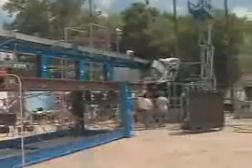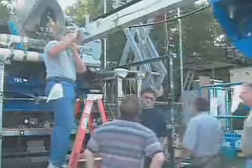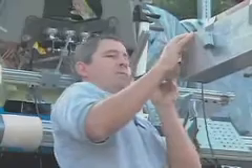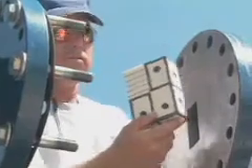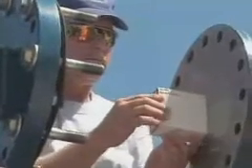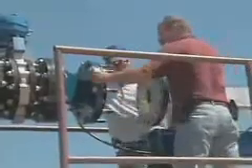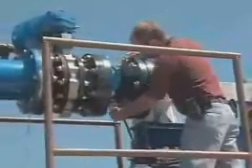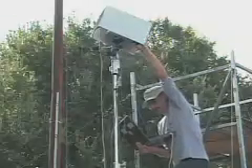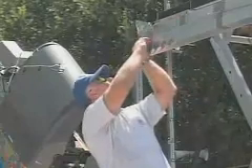This shows the large compressed gas gun outside at Southwest Research. In the background, you see an RCC panel. That's the gray curved structure there. It takes a lot of folks to set up a test and all of the instrumentation, like measuring strains and accelerations, and also measuring everything with high-speed video so we can reconstruct exactly what happened post-test. This shows a technician loading a piece of simulated debris, a piece of foam, into the barrel of the gun. The gun is buttoned up, and a pressure chamber is pulled towards the barrel there. We use a compressed gas to actually fire the foam at the target. What you're going to see in a moment is a foam impact at full speed. And watch carefully.